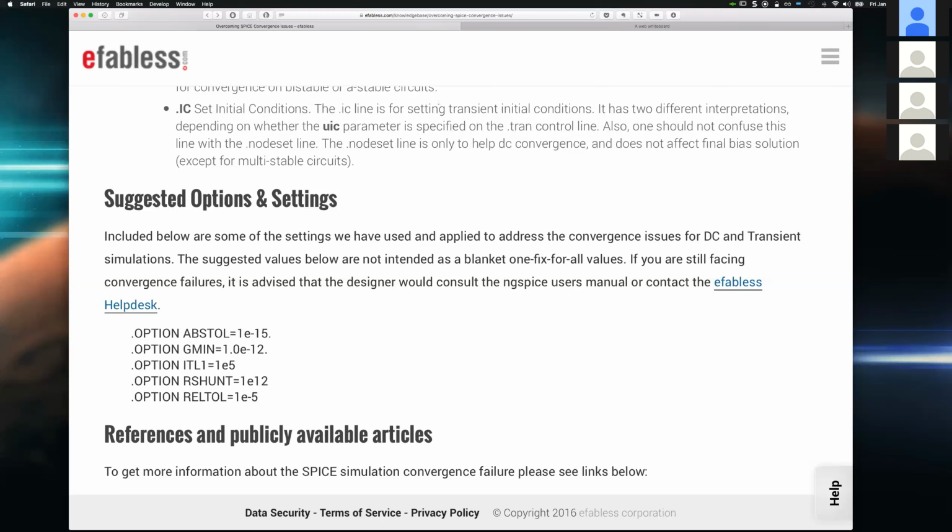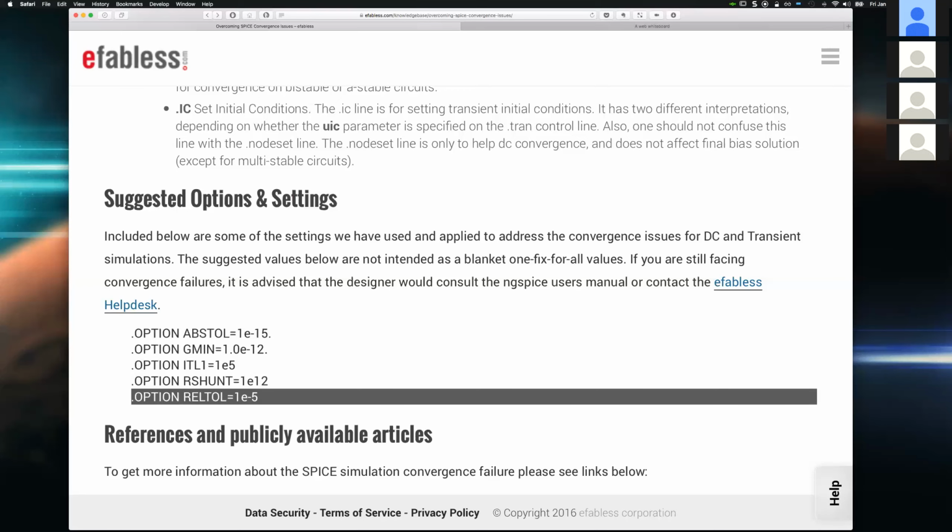Yeah, but the right approach is to find one that works for both through trial and error, guided by certain boundaries. For example, you never put the reltol at 1e-2. I'll tell you, through the experiments you run, it's going to change and cause you to get bad results.